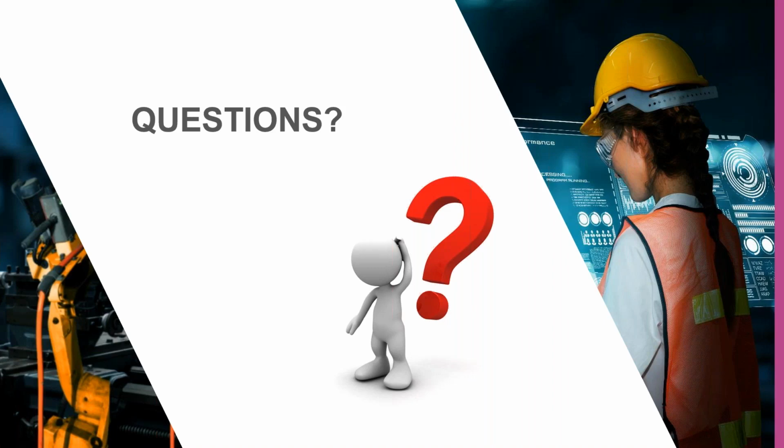But for dimensions, you can use show annotations, and then it'll show up as a list, and then you pick from that list which dimensions you want to show. So hopefully that answers your question.